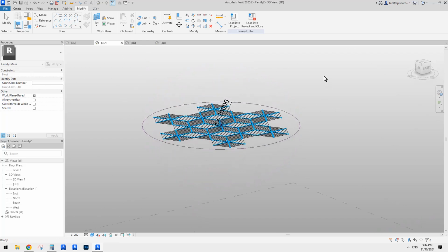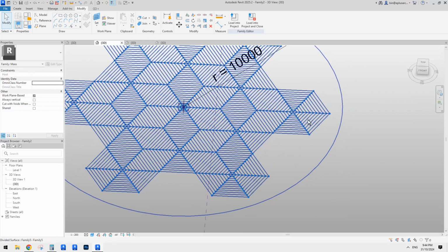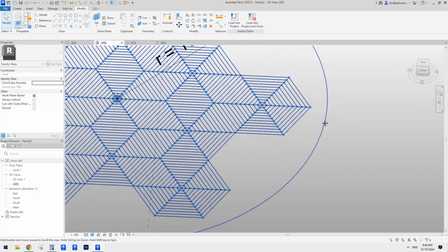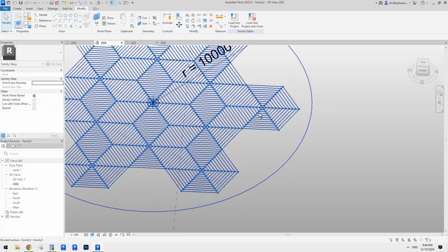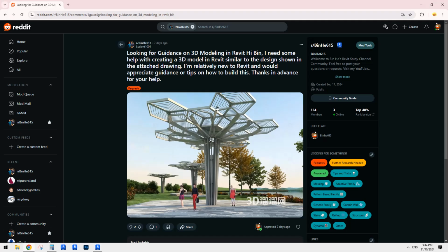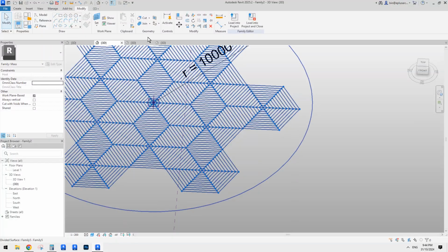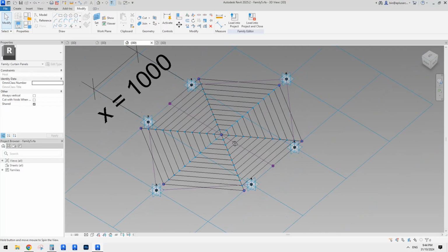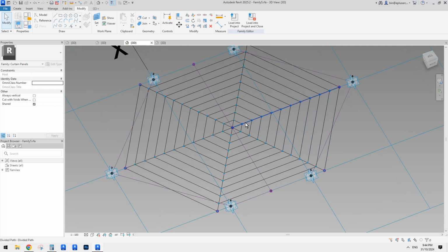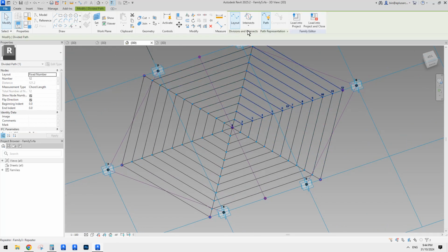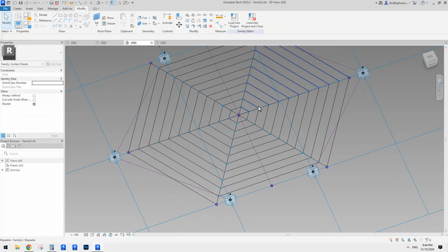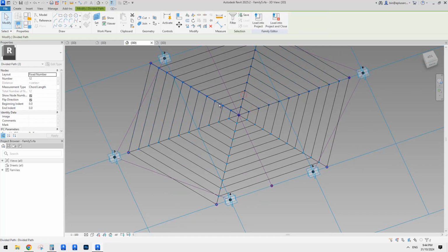Click OK. So now we have this, and of course, we need to hide 3 of the model lines, so you can see 1, 2, 3, 4, 5, 6. So in this one, there's no, right? So that's fine. We can go back here. So no, don't delete. Also if you click on this one, this is a divided path. It's not the one we want to hide. Okay, so let's select all the divided paths for now, and then type HH.